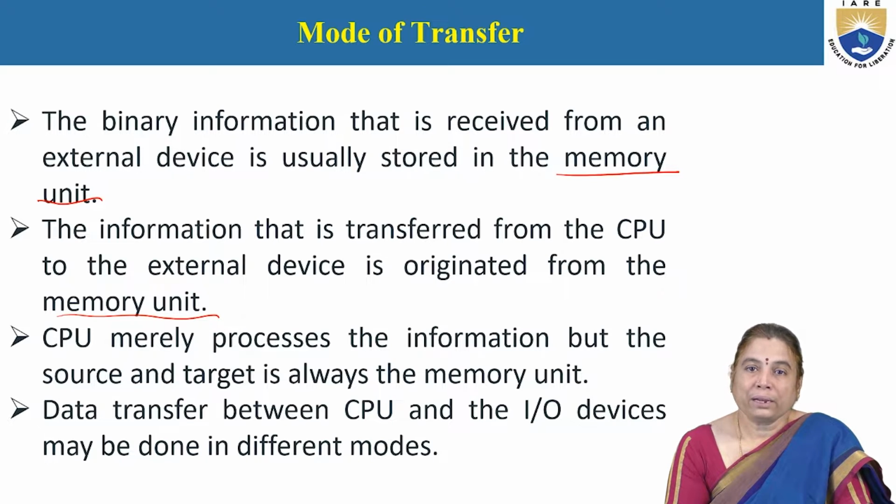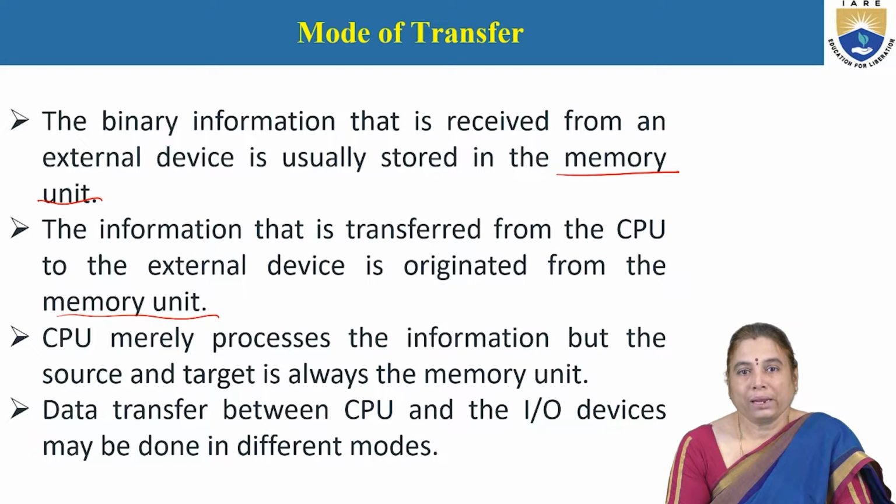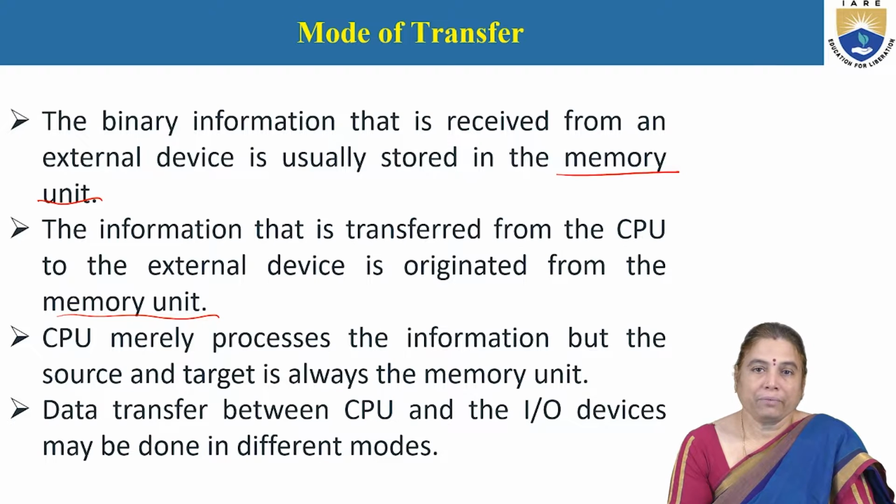Whenever a read operation is applied on the memory, the data from the memory location pointed to by the address register is retrieved into the data register. In case of memory write, the data register content is transferred to the memory location represented by the address register.